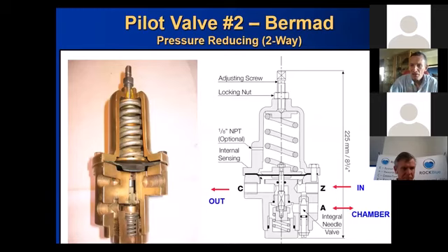Most of the valves have a thing called a pilot, and here's a picture of a pilot. It's about 6 inches, 8 inches long. Unfortunately, most of them are made of brass, which is good for the quality, or bronze. It makes them quite attractive for the scrap merchants, so you have to be a bit careful on sealing your installation in many countries, particularly where I work. You can't leave these things alone. Anything that's made of bronze or brass will disappear if it's not under a 5-ton block of concrete. So the trouble is, without the pilot, the valve is not operational.